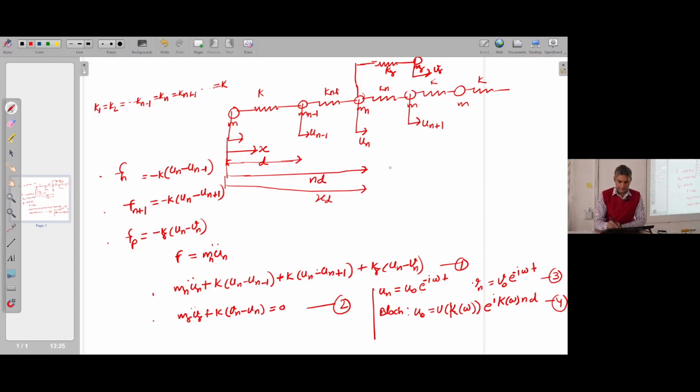So see what we can have, this k, that is the wave number, actually is 2 pi upon lambda. The lambda actually is the wavelength of the vibration wave, right? It may be sound wave, whatever. So this wave number, that is capital K, which is a function of omega, is nothing but 2 pi upon lambda. So actually if lambda is high, then wave number is low, right? Yes, this is the wave number.